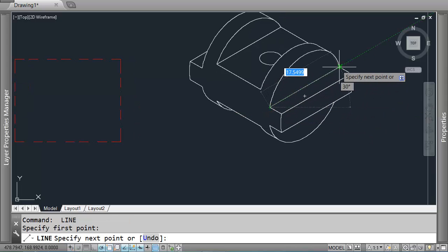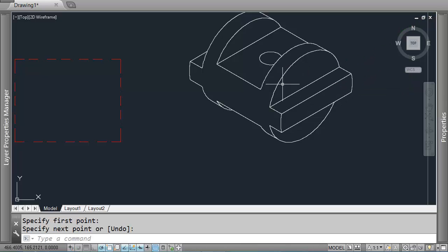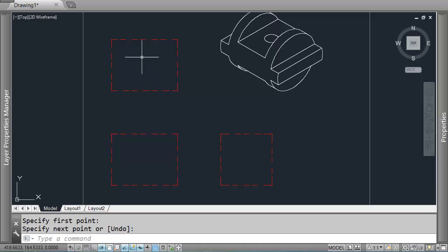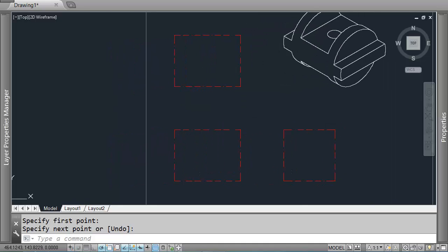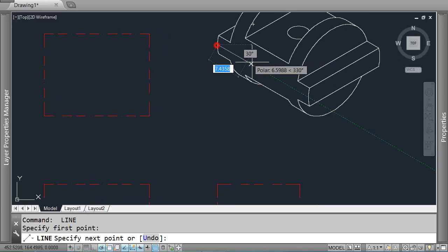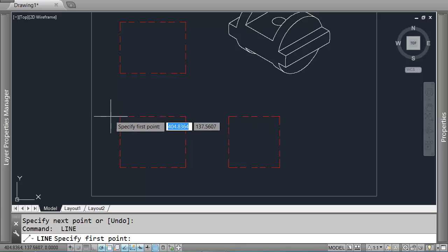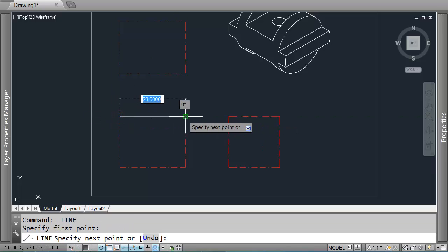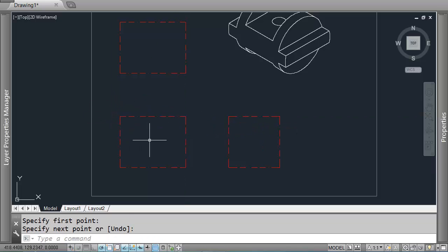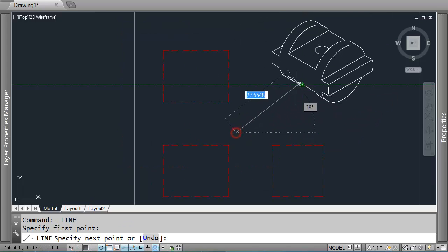So I'm going to show you how you find the true length of that shape, and you'll see that it comes back to what we've often mentioned, which is that in third angle you need to use all of the views that you have in order to define all of the parts of the shape. So to begin, if we have a long length here, 23, I can check the length of this front side and say, okay, this is going to be our front face. This is where we're viewing the object in this direction.